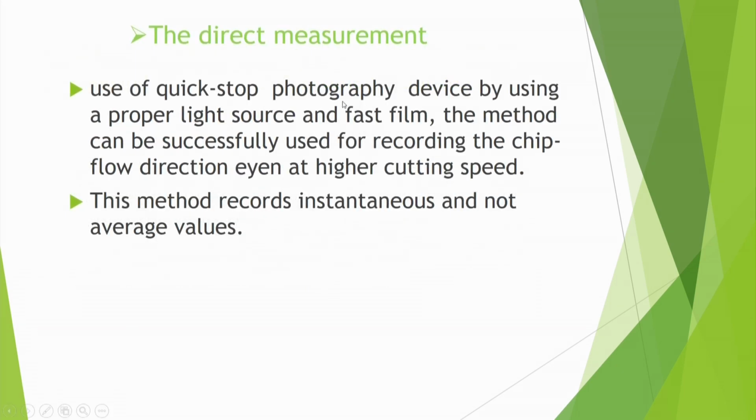Another method is the use of quick stop photography, as I have described in my previous lecture. A proper light source should be there, and some fast film. Nowadays we have high speed cameras. These high speed cameras can also provide the recording and flow direction even at high cutting speed.